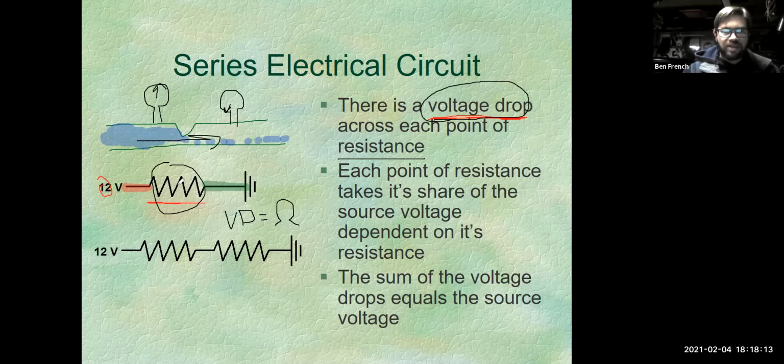Well, this could be the basic schematic of that. I got one defroster grid. It's in series all by itself. That's it. Okay. It's going to drop the voltage over the element, and it shouldn't be dropping the voltage across the wires or the connections leading up to it or the connections going to ground. I should drop that voltage across the component.